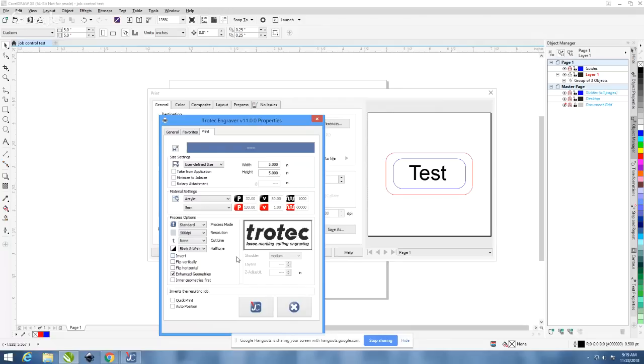In general, deep engraving in a single pass becomes difficult with acrylic because you end up with some molten slag left behind. So for doing that, it's really done best with multiple passes rather than trying to do it all in one shot. And the lens doesn't really matter so much as far as that's concerned. Anything typical for engraving, 1.5 to 2.5 inches, is fine.